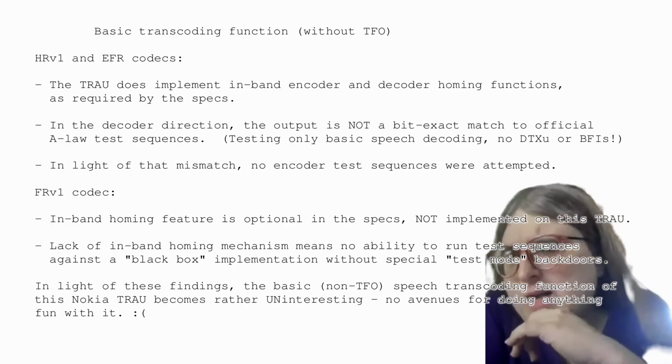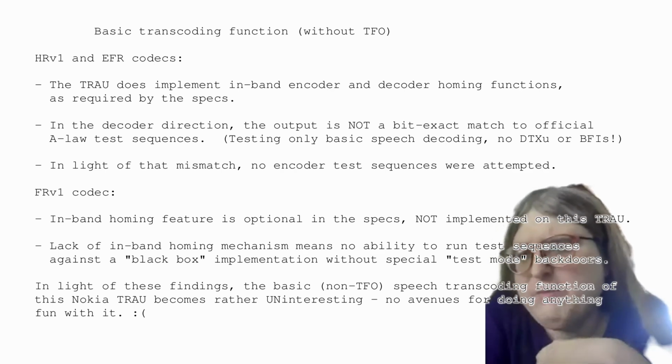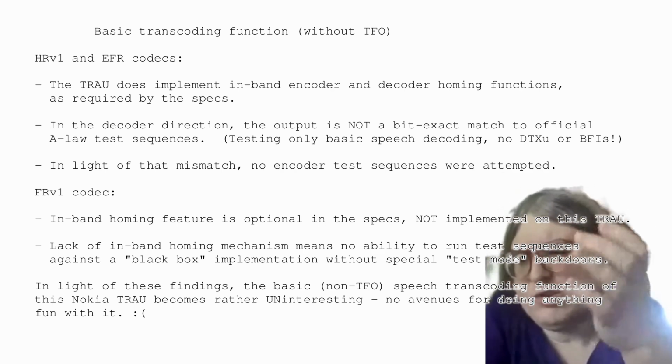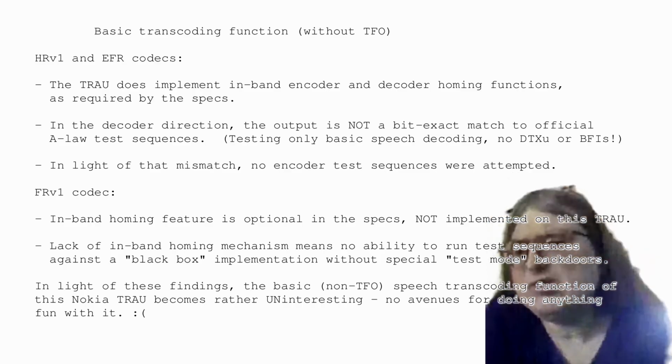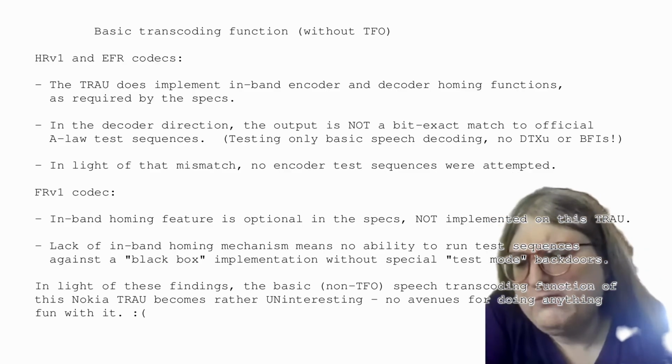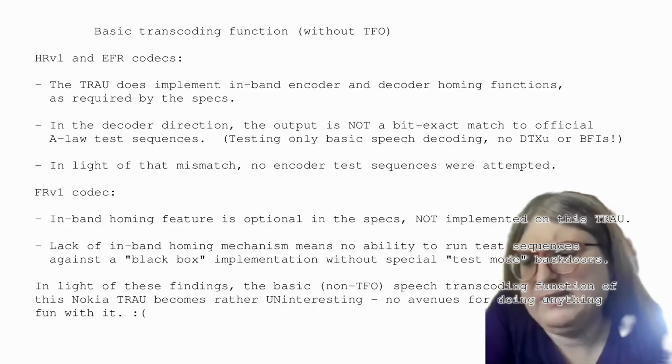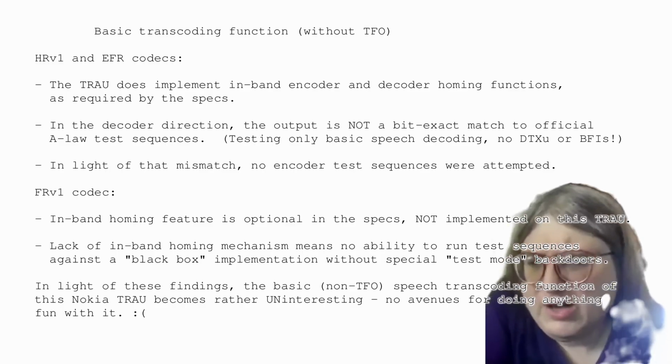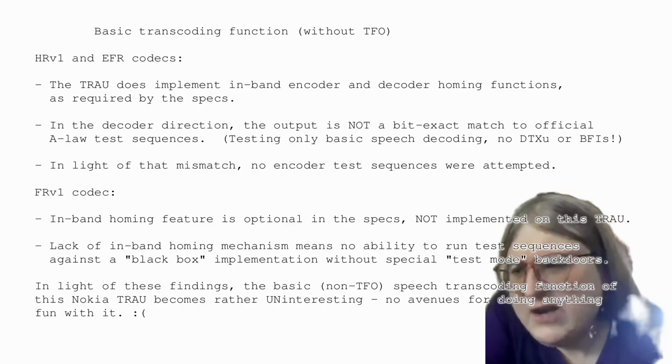The TRAU does implement extra features. Beyond the normal stuff that you have to have in the TRAU, they also have optional stuff like playing with uplink and downlink gains, and then they have dynamic gain adjustment. Then they have the acoustic echo cancellation and whatnot. I have all of that disabled. In the management interface, I disabled all of that.